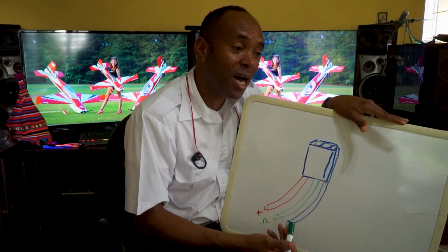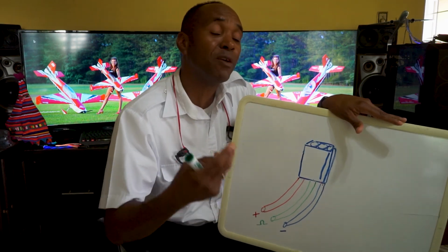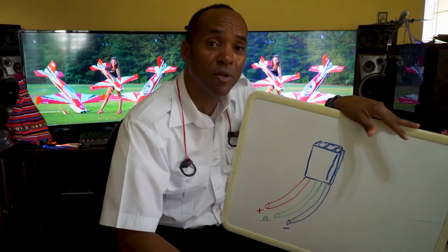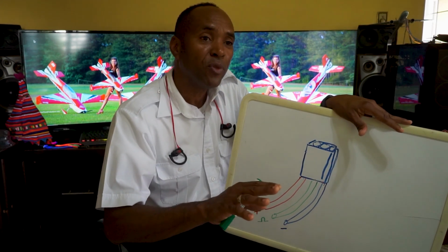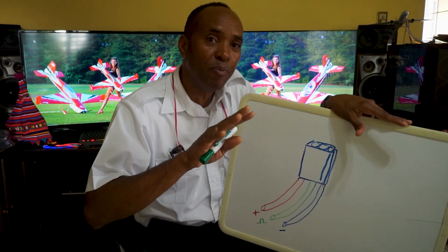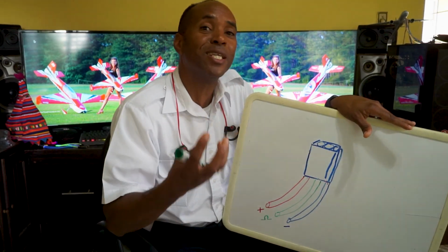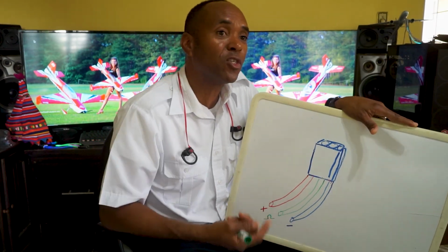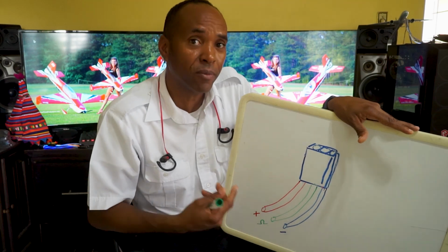So when you know that you have a high current demand in your system, you may have to consider 2 batteries, or probably even an auxiliary battery also. 2 batteries come feeding into the one receiver or into the power distribution box, and so the batteries are big enough, and you have 2 batteries now to deliver the current without a significant voltage drop to the system. And that is how you get the electrical system in a significant size airplane to work.